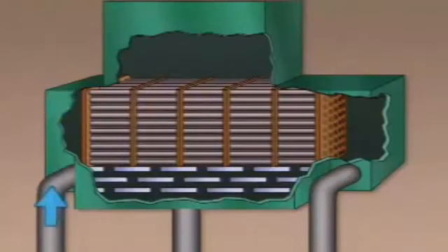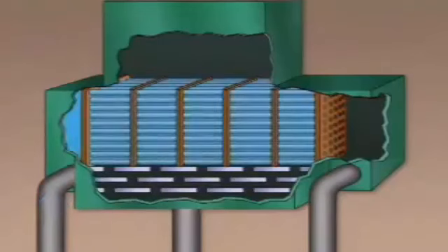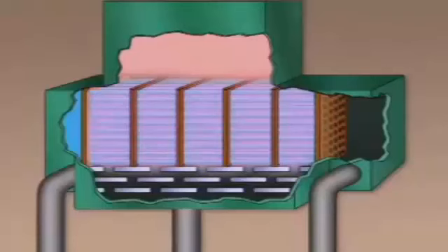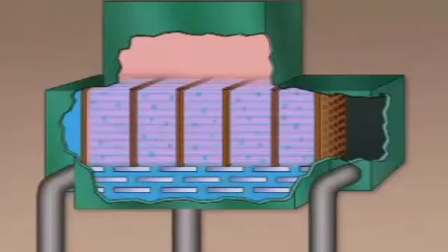During normal operation, circulating water enters the condenser through the circulating water inlet, flows through the inlet water box, and into the circulating water tubes. At the same time, steam enters the condenser through the steam inlet and flows around the circulating water tubes. As the steam makes contact with the cooler tubes, it condenses on the sides of the tubes, and the latent heat in the steam is transferred to the circulating water.